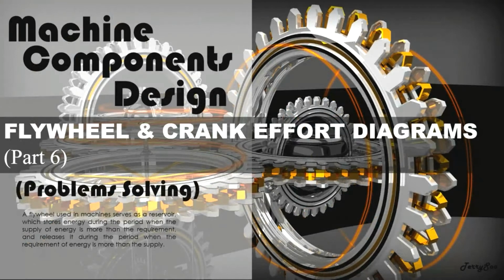This will be the 6th example on flywheel design. The turning moment curve for an engine is represented by the equation T equals 20,000 plus 9,500 sine 2 theta minus 5,700 cos 2 theta Newton meter, where theta is the angle moved by the crank from the inner dead center.